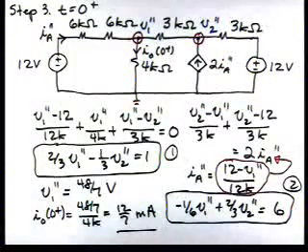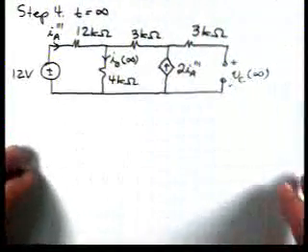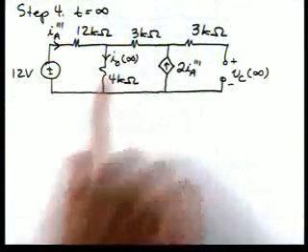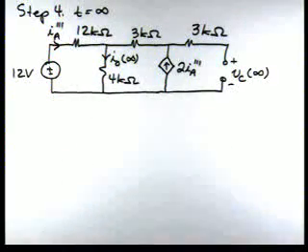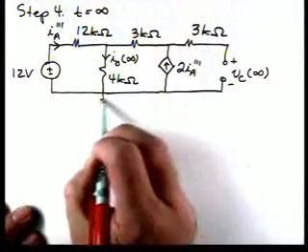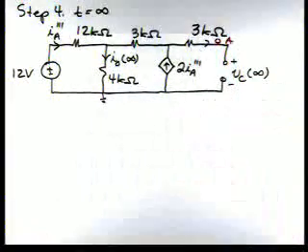Now we need to go to the circuit at t equal infinity. Now we're going to assume the circuit's in steady state again. The capacitor is replaced by an open circuit. And again, we need to find I0 of infinity. I'm going to select this as a reference node. Again, we note this is 0.